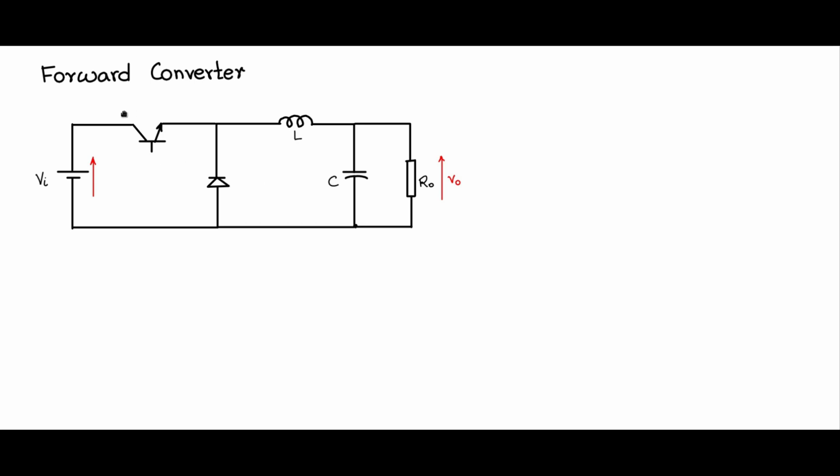Now let me do one thing first. Let me shift this transistor which is on the top rail to the ground rail, because then we need to drive this transistor with respect to the emitter. A lifted up floating emitter is much more difficult to drive than a grounded emitter. So let me make some space here and let me place the BJT here. Now the emitter is on the ground side, same direction of the current flow. You see that the current flows in the same direction. So only it is on the return rail.